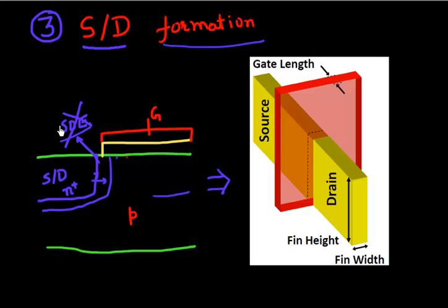I described earlier that we had these multiple implants and how cool it was, but let me admit, I was really kidding. The implants in a planar device are really a mess, and to control these multiple implants and their diffusion was a real mess. So as compared to 3 implants, I'm managing with just one source drain implant in my FinFET device. That's good news, and that should be pretty exciting.